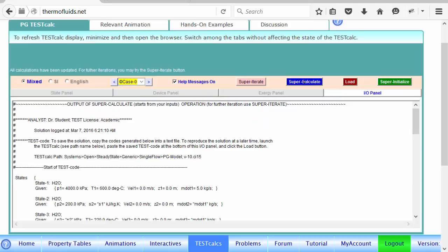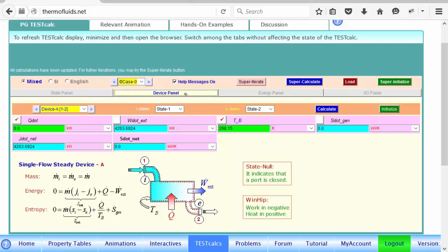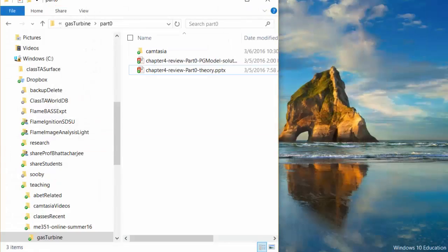Now, steam is being treated as a perfect gas, and all the solutions are produced. I want to write those down because in a separate problem, we are going to handle steam with the appropriate model, which is the PC or phase change model, and see the more accurate answer compared to this PG model answer. So if we use H2O, we get an ideal turbine output of 4264.